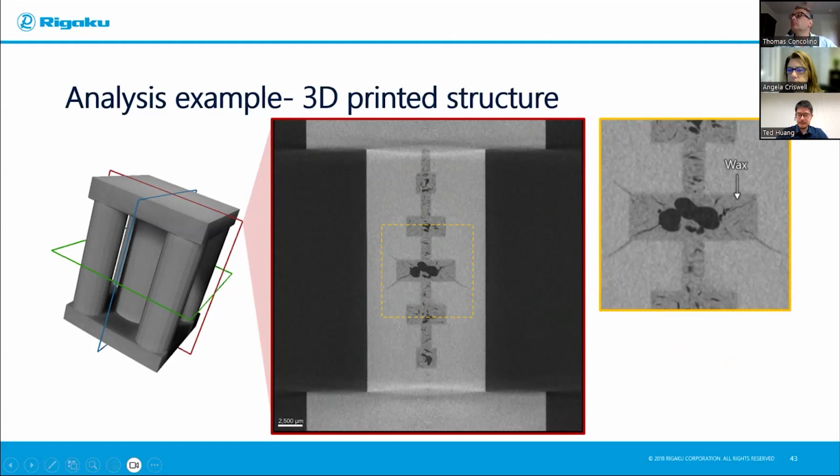I didn't expect it. And since they got trapped inside, and the wax and the material we use to print definitely have different thermal expansion, when it cools down, the wax contracts and forms all those pores and cracks. And that contraction also gives force, right? The different contraction between materials gives force. And that actually leads to the crack growing into the actual 3D printed structure.